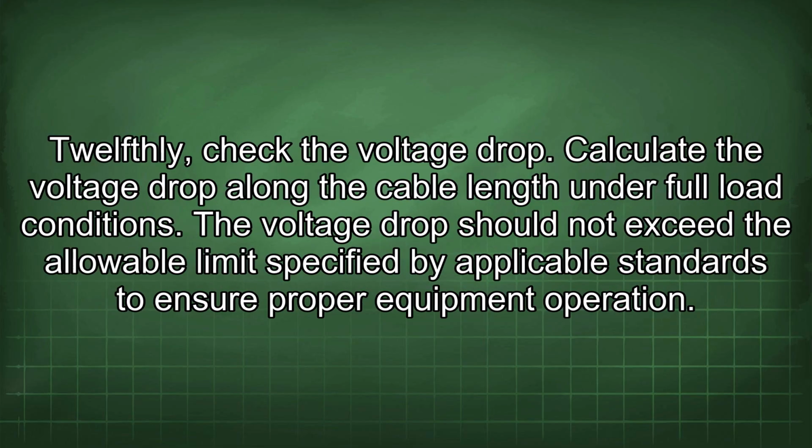12thly, check the voltage drop. Calculate the voltage drop along the cable length under full load conditions. The voltage drop should not exceed the allowable limit specified by applicable standards to ensure proper equipment operation.